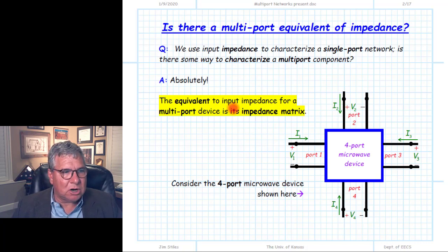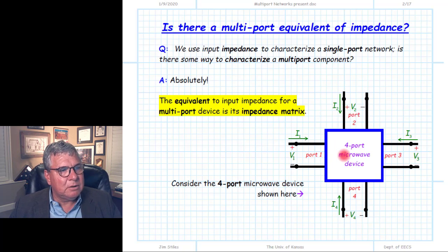So to understand what those are, first we go through for a multiport device. In this case, I show 4, although this could be any arbitrary number of ports. We define a port plane for each port, a location where we define a voltage. And notice these are complex voltages and currents. So we're talking about time harmonic signals here. These are not DC currents and voltages. These are time harmonic. Complex numbers describing the magnitude and relative phase of the oscillations of voltage and current now at each of these 4 points. And of course, those values therefore will be dependent on the frequency of that oscillation, omega.